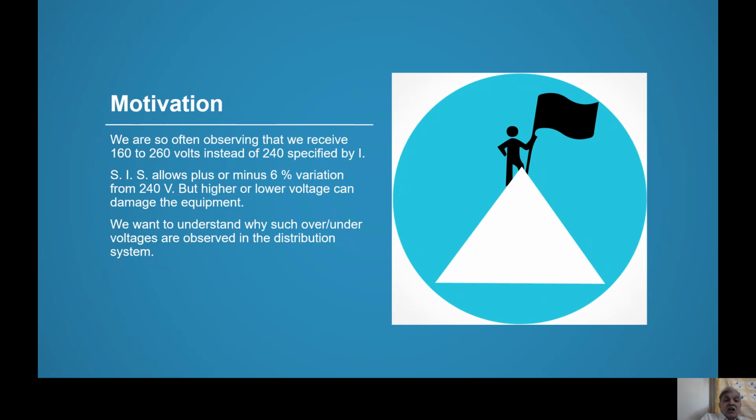because while the motor is running, if the voltage is low, mechanical power is constant, therefore electrical input is also constant. V I cos phi is constant, so if V decreases, I has to increase, right?